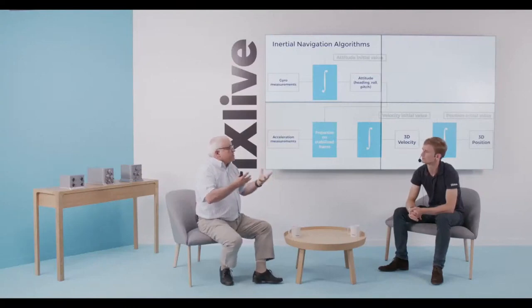Yes, that's right. And another problem that we may have with the magnetometer is the fact that if you are not measuring only the Earth's magnetic field, you have to compensate for all the magnetic fields which are disturbing this Earth's magnetic field. So it may come from the INS itself, from the vehicle on which it's mounted, or from the environment around the vehicle.